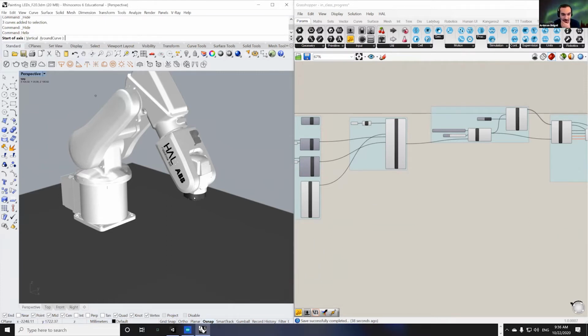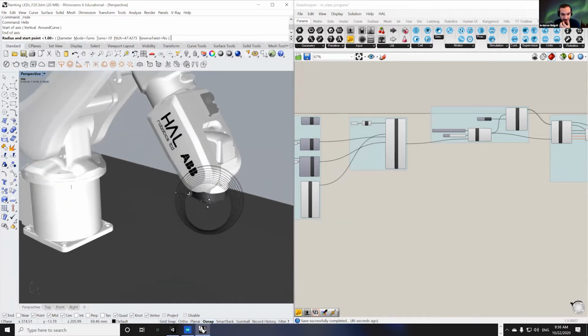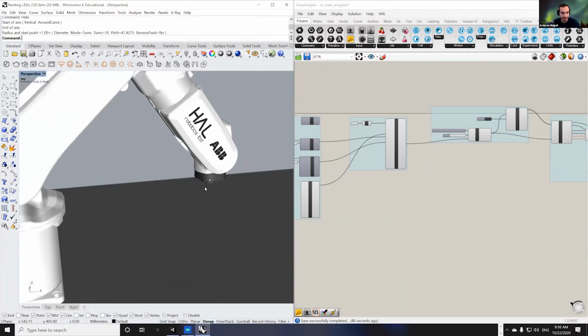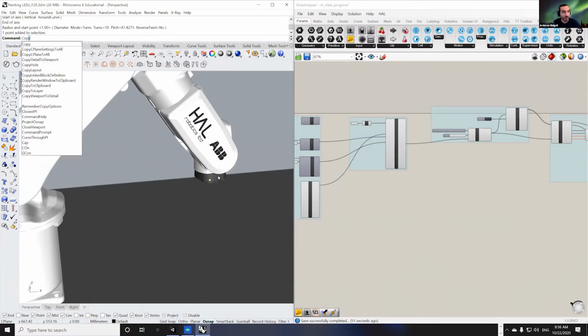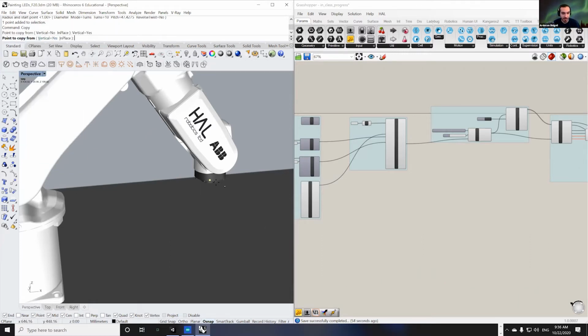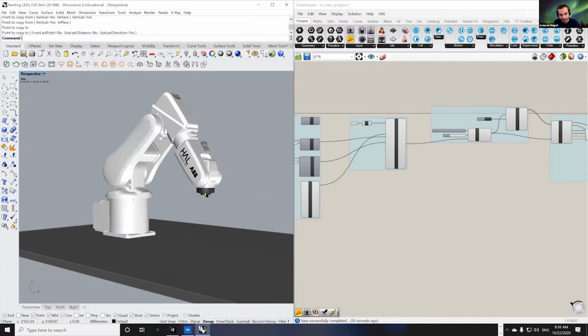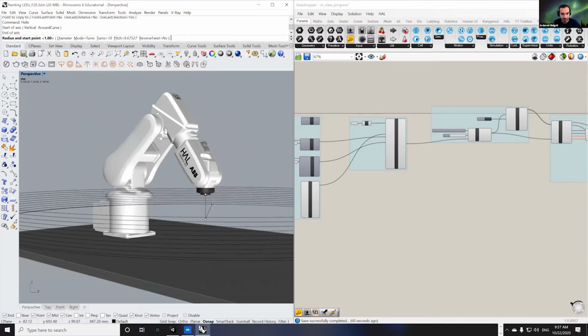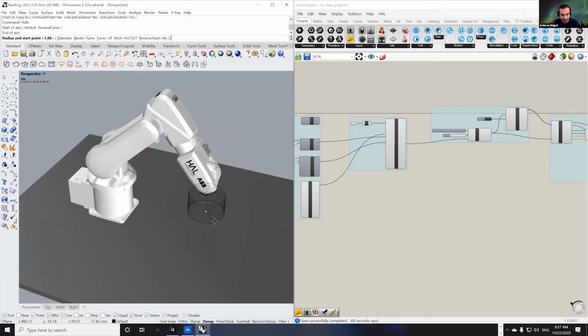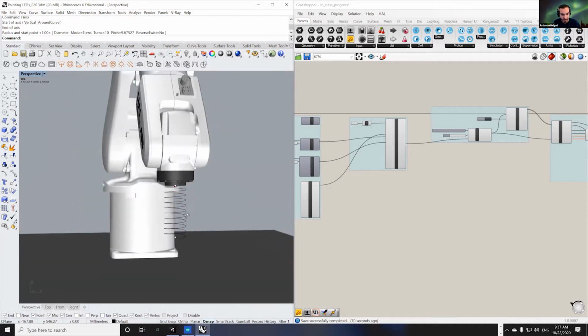So in Rhino, you have this option to draw a helix. So basically, you select a point. I selected the point that I just selected, and you can actually make a helix like this. My suggestion is actually to draw 2 points. So I'm going to copy that point, make a vertical copy of that one. So I'll have 2 points, one exactly above the other one. Now I can use that helix command. I'll select the first one, I'll select the second one, and then I can actually set the radius for something like this. So I will get something like this.